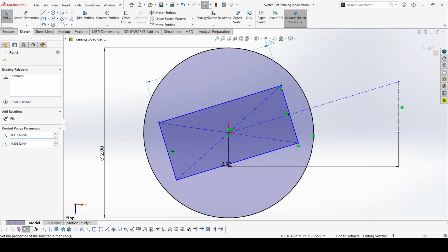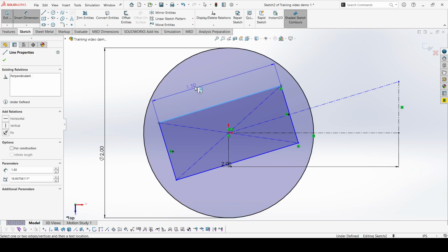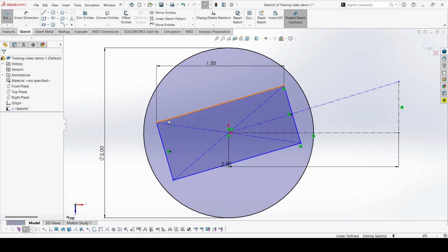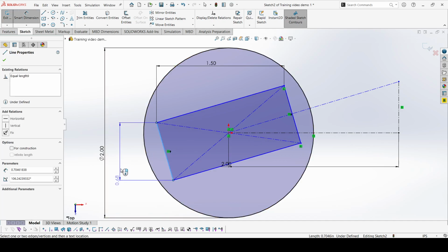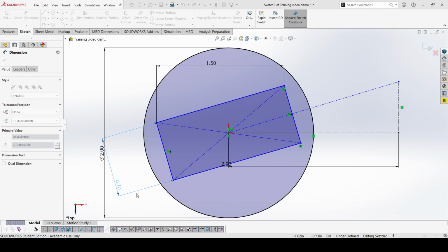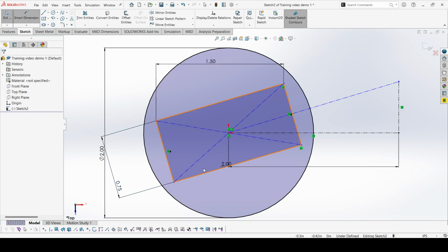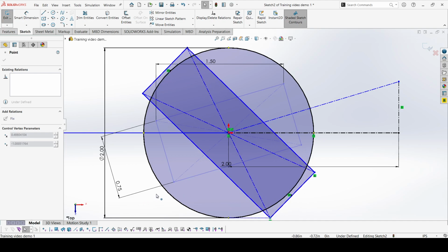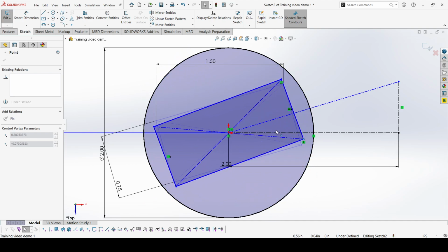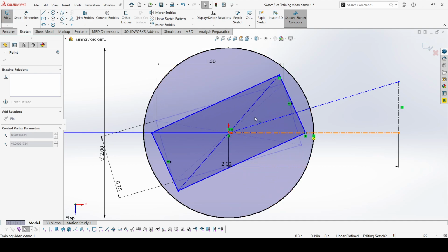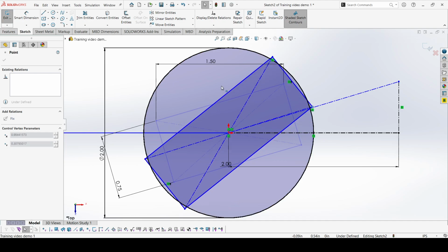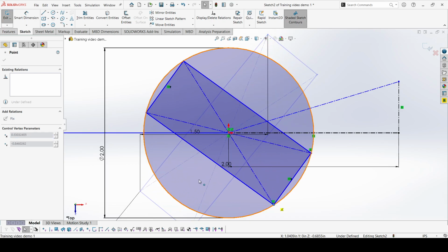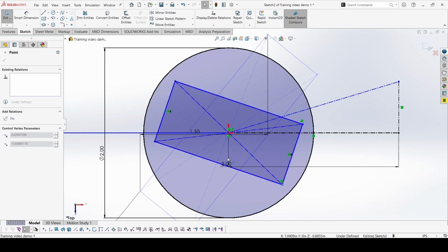But yeah, actually, the thing I was talking about with dimensioning. This is something you want to make sure you don't do by accident. I'm gonna do this. Now, you'll notice, even if I mark this as 0.7, actually 0.75, you'll notice something really cool. This rectangle, that side length is changing. Why is it? Because what's actually happening is that side length isn't defined. Rather, the x distance between this point and this point is defined as 1.5 inches. So this thing will expand depending on its orientation.